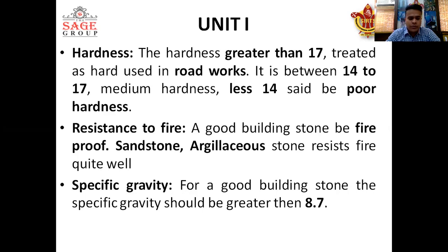Now let me tell you about the resistance to fire. A good building stone should be fireproof, as we know that igneous rocks are formed by volcanic eruptions and the cooling of hot magma lava, which converts into solid rock. So it is clear that a good building stone should be fire resistant. Sandstone and argillaceous rocks are the best examples of fire resisting stone.